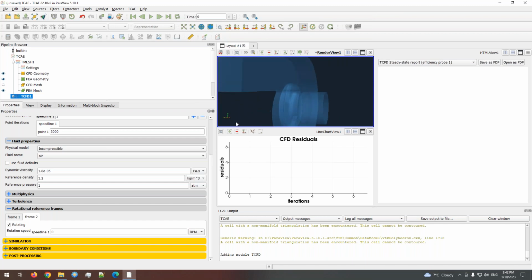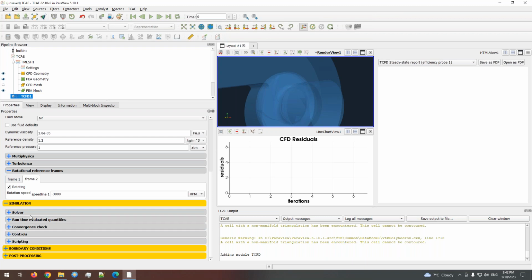We have the axis pointing to the y-axis. If you point the thumb along it, your fingers show the positive direction of the revolution, but we need the opposite rotation direction. Therefore we need to set minus, and this fan is designed to operate at 300,000 RPM. So let's set 300,000.